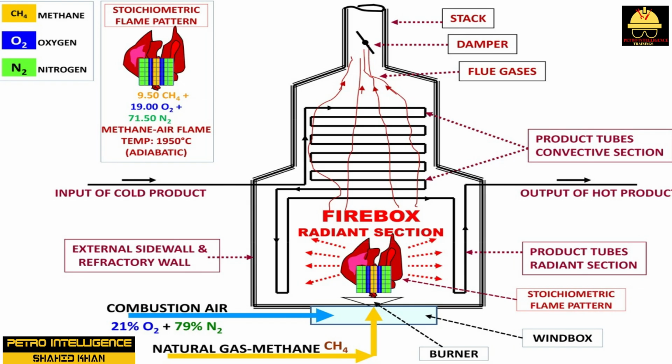Modern burner design consumes 100% of the fuel with a nominal excess of 10 to 15% oxygen. Excess oxygen in the furnace is carefully controlled as it enters the secondary and primary registers. This control takes place as the fuel and primary air mix at the burner and is enhanced by adjustments on the secondary air registers mounted on the outside of the burner.